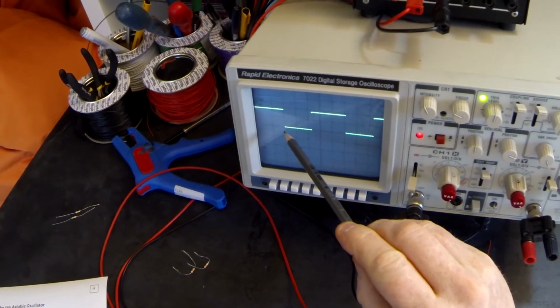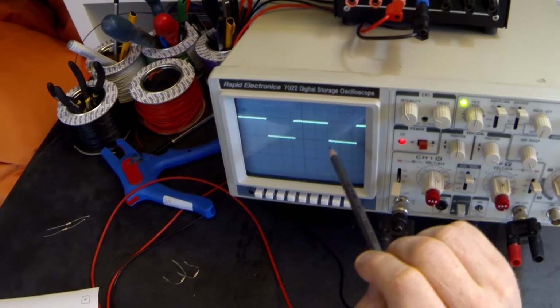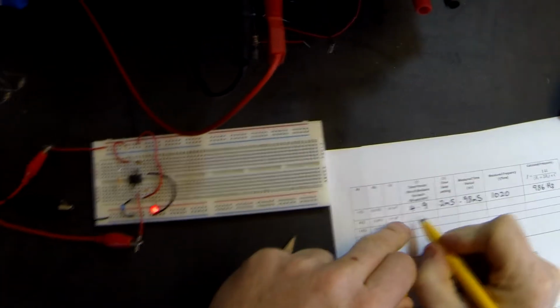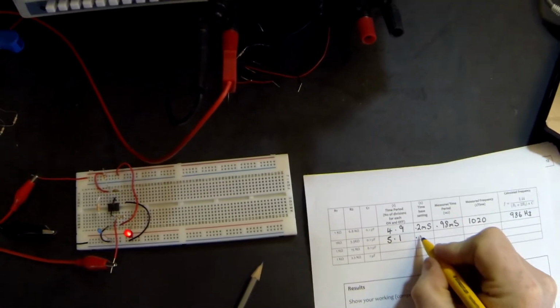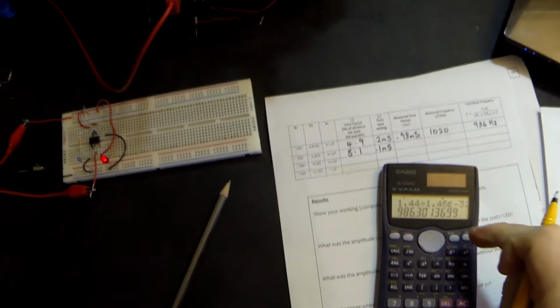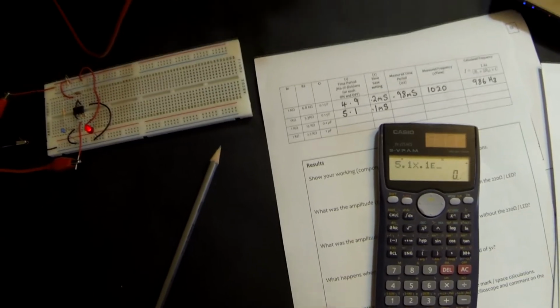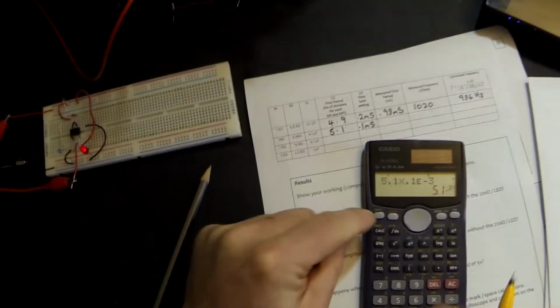And I'm starting at the bottom, so I'm going from there to there. And I go 1 division, 2 divisions, 3 divisions, 4 divisions, 5 divisions, probably 5.1. So we now have 5.1 divisions. Each division is worth 0.1 milliseconds. Using my calculator, I have 5.1 divisions times 0.1 exponent minus 3 for milli equals, now it's given me it in times 10 to the minus 4, so let's go shift engineering, 0.51